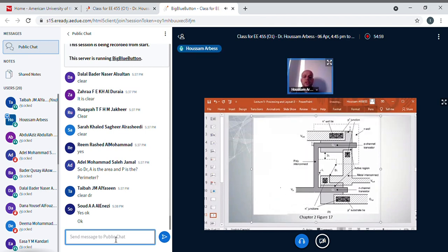Well, here they mentioned already that this gray here is P plus. This dark gray here is polysilicon. This one here is N plus. What else? The layer here, what you can see, is the metal.